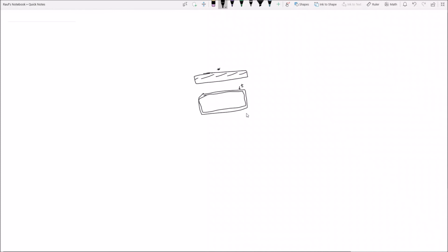Now you want to put stuff in here. That's where your parts will go. So you need to know the external length and width of your enclosure. Then you need to know the thickness so you can know the internal width and internal length that we care about. This is where your components will go. If you have a printed circuit board in here with certain dimensions, and you're trying to keep the circuit in place, then you want to think about the method that this circuit will be held in place together with the upper or lower enclosure.